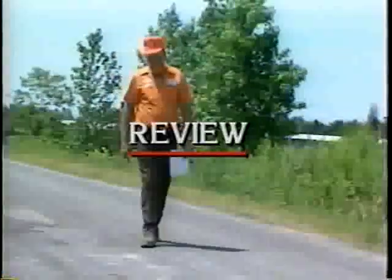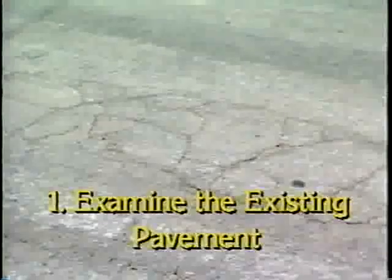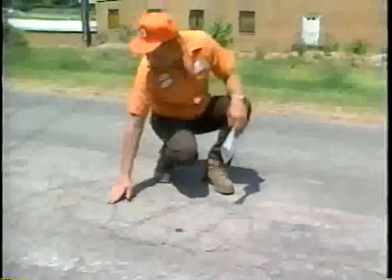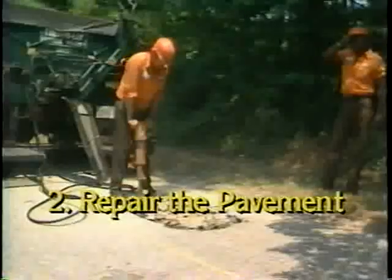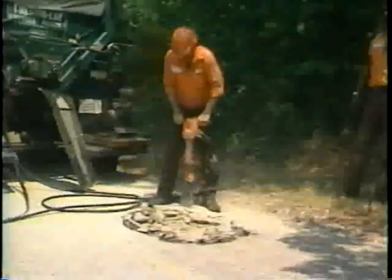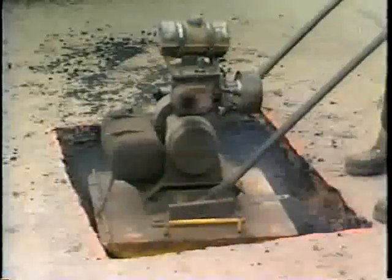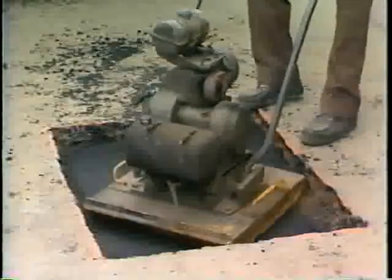Let's briefly review the 7-step procedure for installing an asphalt chip seal. Step 1. Examine the existing pavement. Examine the pavement for surface distresses and drainage problems. Step 2. Repair the pavement. Complete pavement and drainage repairs prior to the installation of a chip seal. If these distresses are not repaired prior to the seal placement, they may reappear soon afterward.